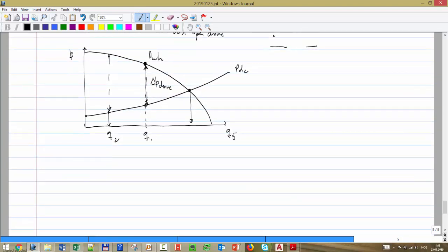Now that's okay, that's the whole point. What we were doing in our calculation, this rate here, you remember what was the maximum rate that we can produce? What name did we assign to that rate? The potential, right? In every reservoir pressure, I had a potential, which was the maximum rate that I can produce.